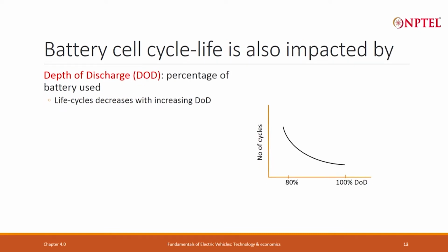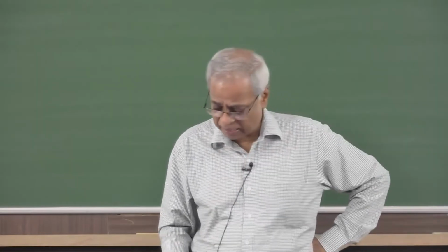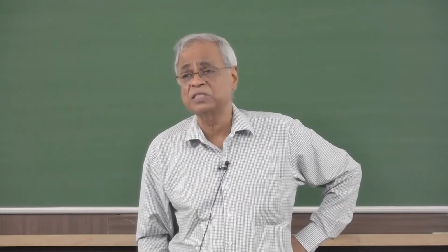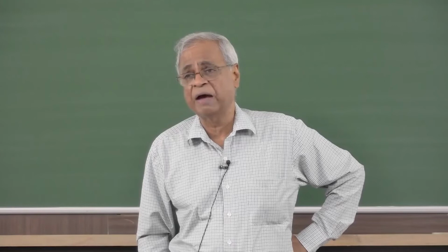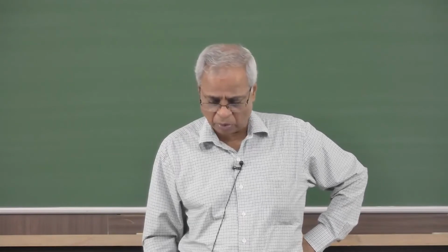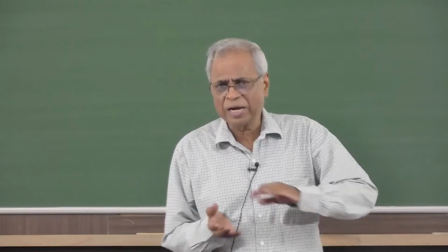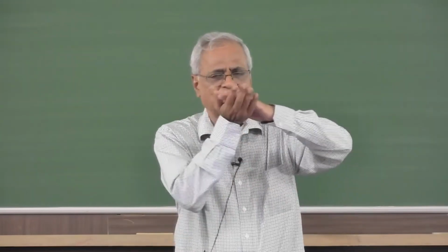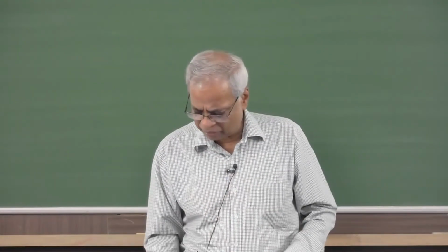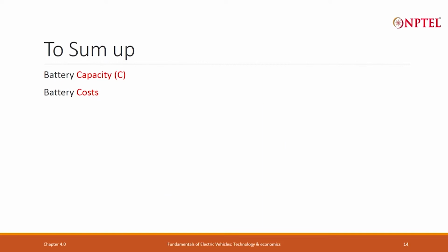Depth of discharge, 100% gives you very few cycles, 80% gives you good cycles, but 75-85% will also give you a decent cycle. So, typically 80 to 85%, they are good quality batteries, which you can discharge to 90% depth of discharge and still work all right. So, I talked about how you leave the window at the top or at the bottom. I am just repeating it.